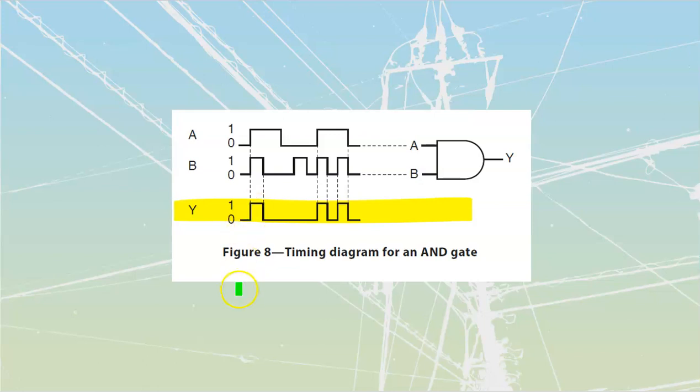So in this case, if I'm trying to say what's turned Y on, I can follow that through and say that what turns Y on in this case is when A and B are both high at the same time. Check that over here. Yep, same thing that's turned it on. Check that over here. Yep, same thing over here that's going to turn that on. In both cases, A and B high is going to give me a high Y output.